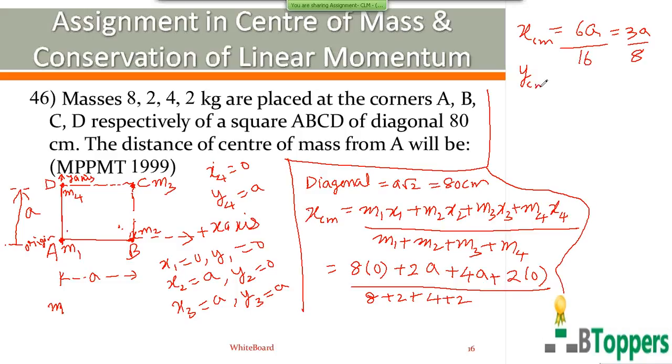The y coordinate of the center of mass, in a similar way, you can write as M1 y1 plus M2 y2 plus M3 y3 plus M4 y4, divided by M1 plus M2 plus M3 plus M4.